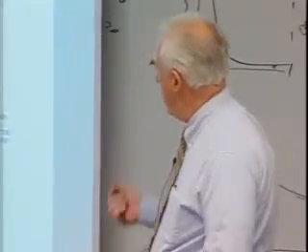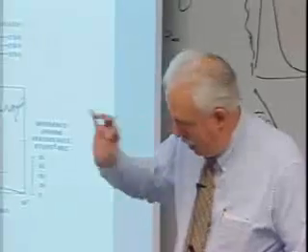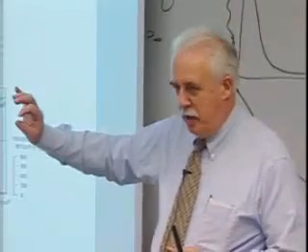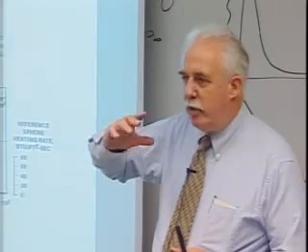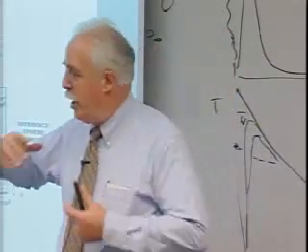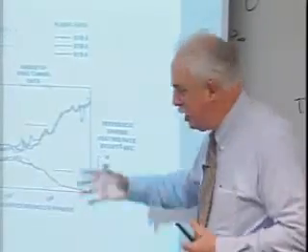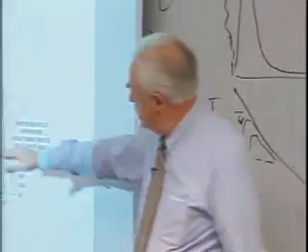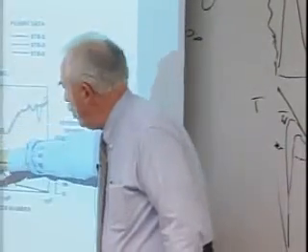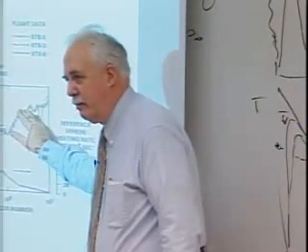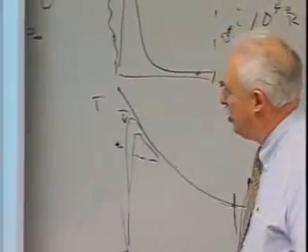There are in ballistic facilities, if you have a particle traveling or a vehicle traveling at high speed, eventually your wake goes transitional and turbulent. As you increase the Reynolds number, that moves forward. As that moves forward, you get more mixing. As you get more mixing, the gas in the wake gets hotter, and I believe that's fundamentally what's going on, and it's very repeatable. Okay. We cannot get this in the wind tunnel. Okay? Okay, now we'll go to TPS.